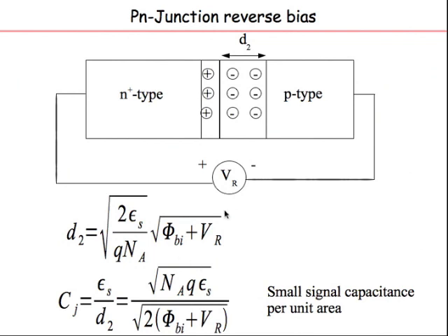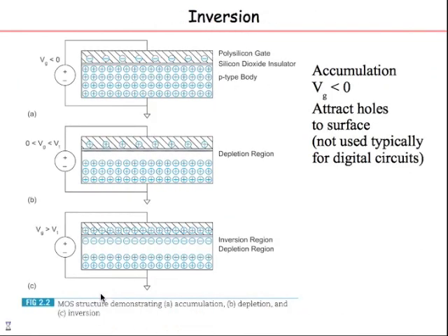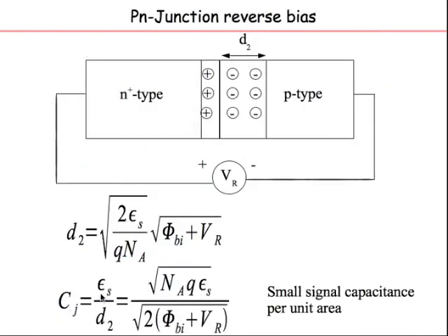So what this equation is telling me is, at some particular point, if I give a very small AC signal, what is the capacitance seen by that signal? That is the small signal capacitance. Clearly in analog circuits, small signal analysis is very commonly used. In digital circuits, we don't use small signal analysis. But still this equation is useful just to keep in mind how it affects.